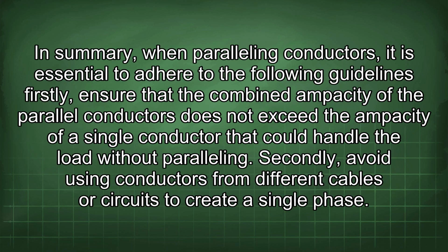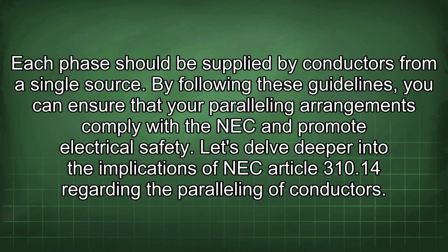In summary, when paralleling conductors, it is essential to adhere to the following guidelines. Firstly, ensure that the combined ampacity of the parallel conductors does not exceed the ampacity of a single conductor that could handle the load without paralleling. Secondly, avoid using conductors from different cables or circuits to create a single phase. Each phase should be supplied by conductors from a single source. By following these guidelines, you can ensure that your paralleling arrangements comply with the NEC and promote electrical safety.